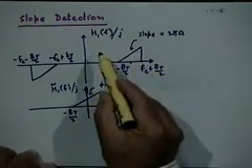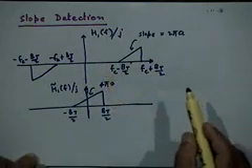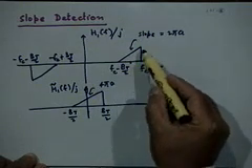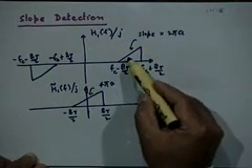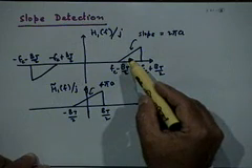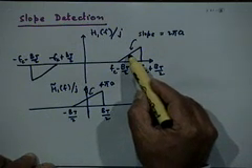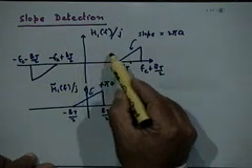This circuit is followed by an envelope detector whose output is proportional to the modulus of this, and therefore the output is proportional to the frequency deviation of the input signal as we want, but with the difficulty that at the carrier frequency the response is not 0 but some finite value.